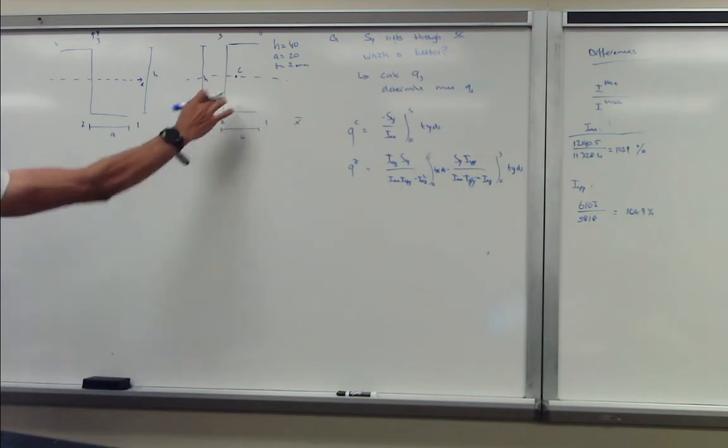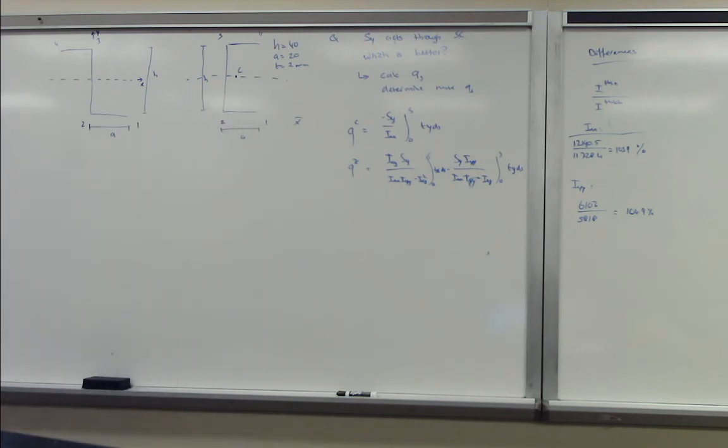I think we did this already one time before, so let's focus on the Qz section first. We're going to use 1, 2, 3, 4 as coordinate systems, and we start at point 1 or point 4 because we know our start shear flow at that location is 0. So let's do segment 1, 2. We have to come up with the x-axis and y-axis coordinate system.